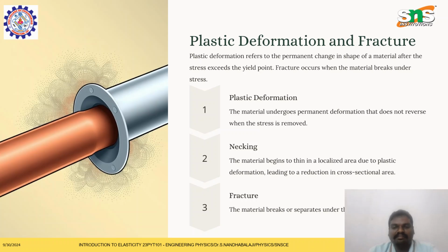Necking: the material begins to thin in a localized area due to plastic deformation, leading to a reduction in cross-sectional area. Fracture: the material breaks or separates.